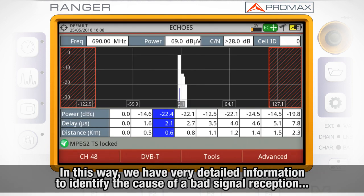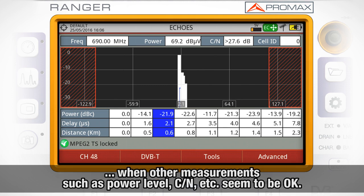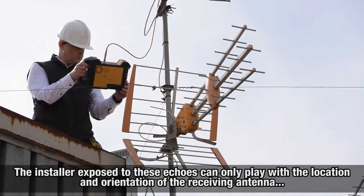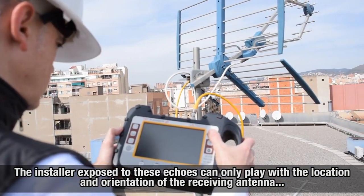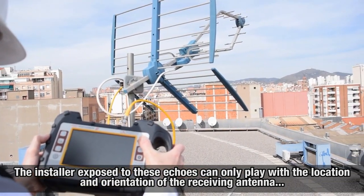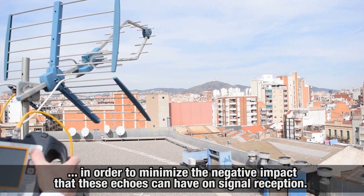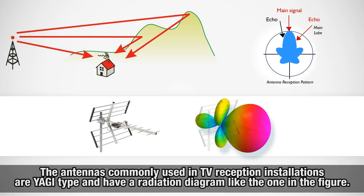In this way, we have very detailed information to identify the cause of a bad signal reception, when other measurements, such as power level, carrier to noise, etc., seem to be okay. The installer exposed to these echoes can only play with the location and orientation of the receiving antenna, in order to minimize the negative impact that these echoes can have on signal reception. The antennas commonly used in TV reception installations are Yagi type and have a radiation diagram like the one in the figure.